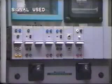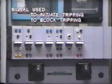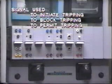In contrast, the on-off system must be checked at regular intervals, say monthly, to ensure that it will work when required. The signal itself may be used in several different ways. To initiate tripping, that is, direct transfer tripping. To block tripping, or to permit tripping.